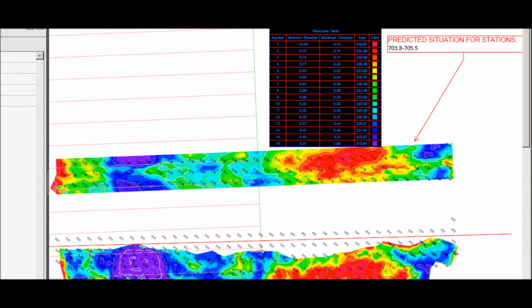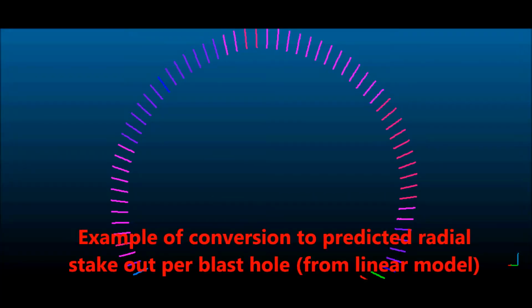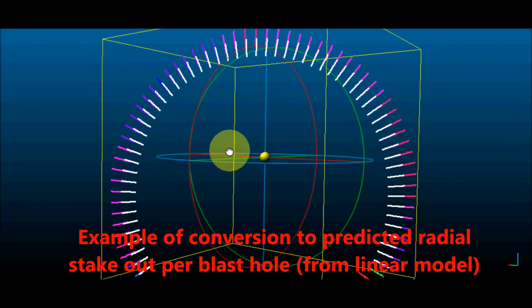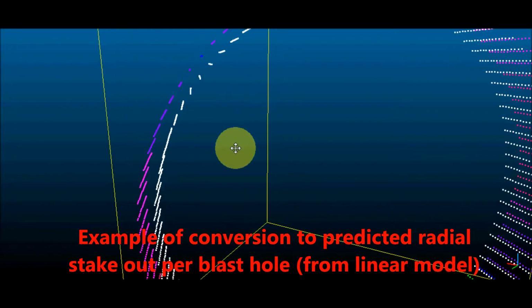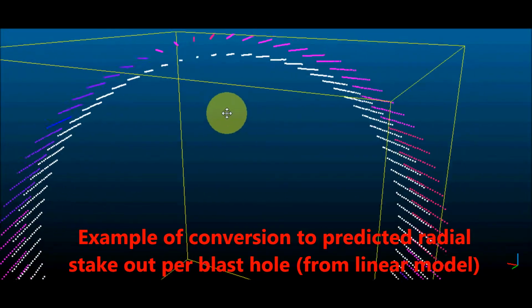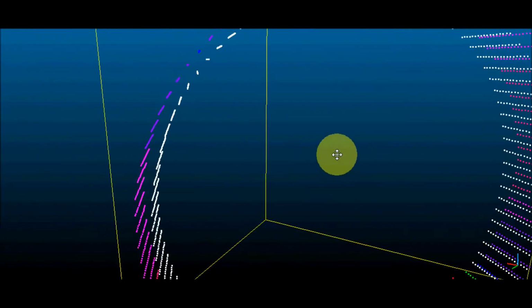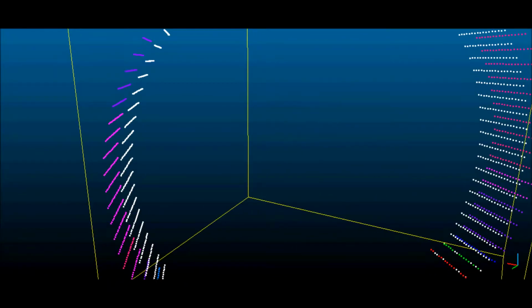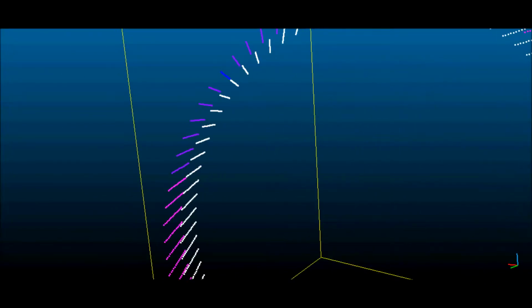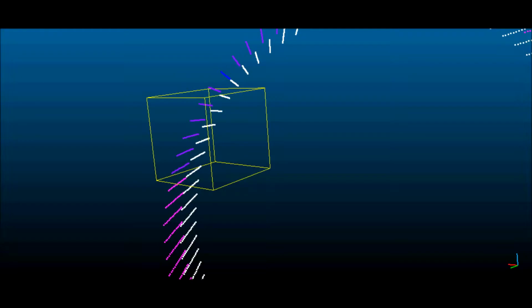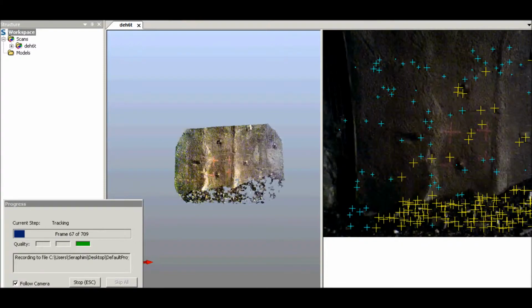The point cloud of each excavation is recalled from the database and probability models are calculated. The location and elevation of upcoming overbreak damage are produced statistically. Based on the predicted situation, targeted adjustments are defined regarding the parametric offset of the drilling stakeout. The theoretical excavation line, or the lattice girder that is usually placed at its theoretical position, is used as a reference. In addition, a third graph is finally produced, presenting the predicted damage per blast hole in a linear or nonlinear analysis.